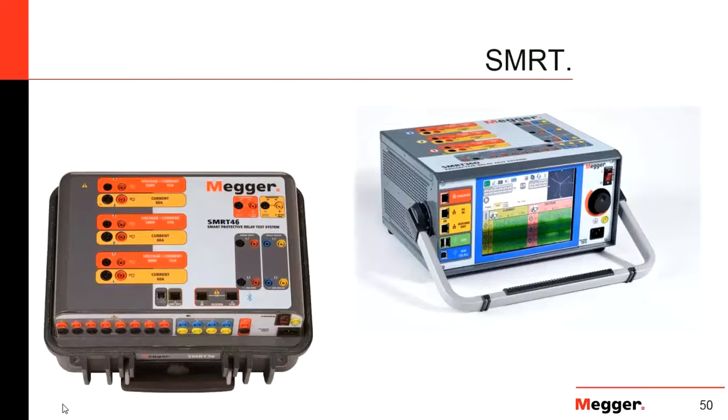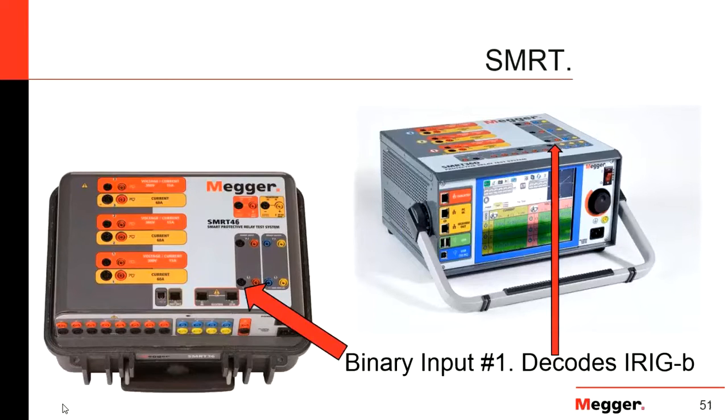To do this test, Megger has a very nice line of relay test sets. Why is it good for the end-to-end testing that we're talking about now? Because we have a built-in IRIG-B decoder in binary input number 1, which can be used with either an external GPS device or to decode the IRIG-B signal that is running in many substations. So it's a very good tool.